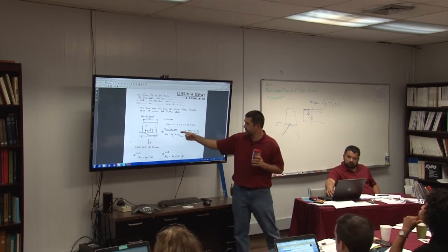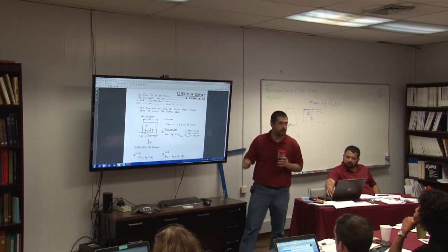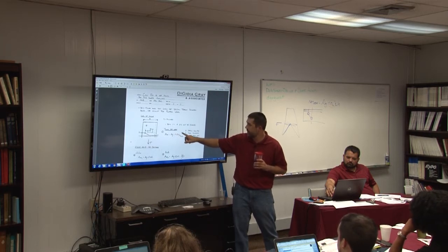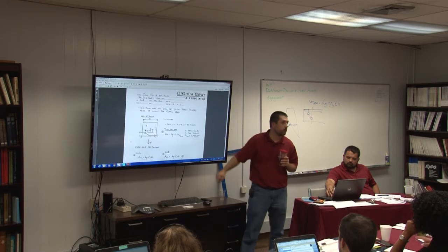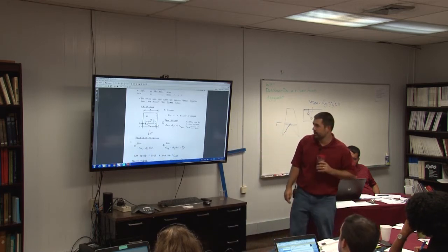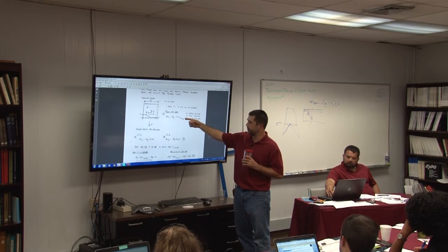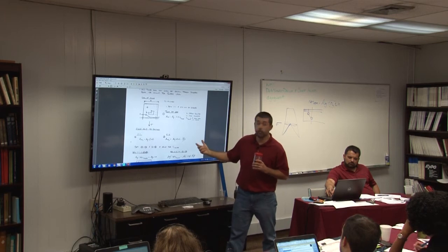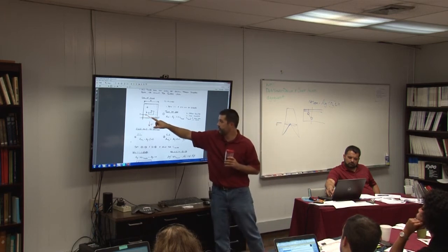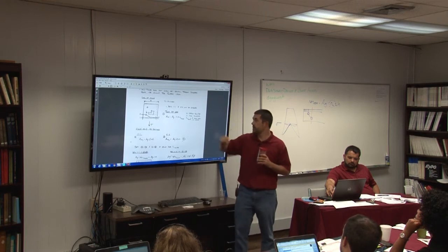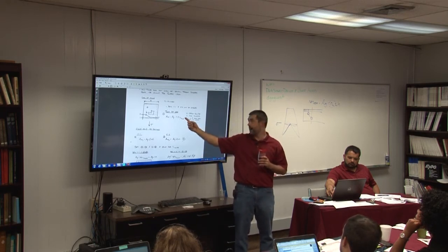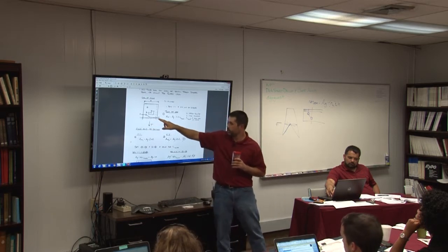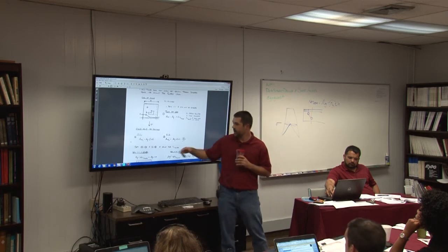Recall that the equation in Tower for net area is the gross area minus the hole diameter times the thickness times what I'm calling here n sub h tower, the number of holes that you input into Tower. This is the equation that Tower uses. What I need to do is figure out the appropriate equations to calculate the net area for both of these failure planes and set them equal to this equation and back solve for the number of holes for Tower.